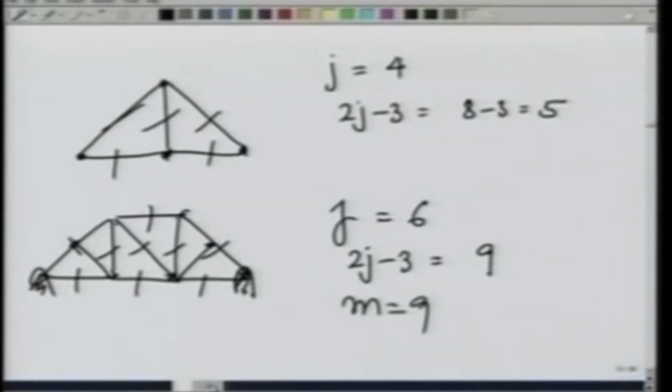You notice that both the ends are put on a fixed point. Actually, this makes the system indeterminate because the number of external forces is now 4. We could make it determinate by putting the right hand side of the system on a wheel or on a roller.